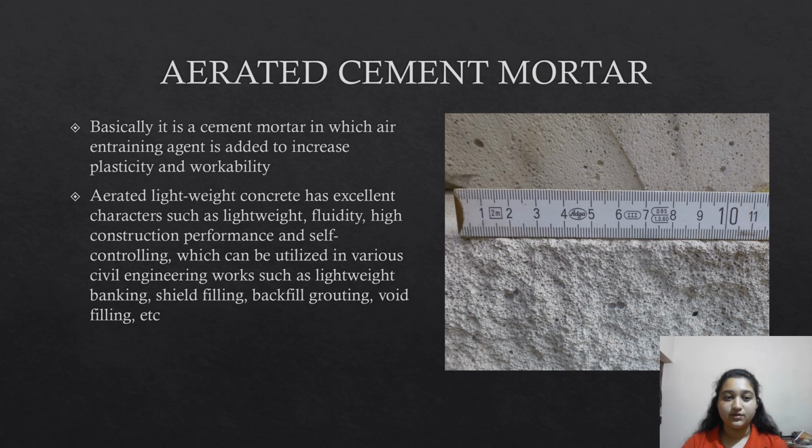Aerated cement mortar. Basically, it is a cement mortar in which an entraining agent is added to increase plasticity and workability. Aerated lightweight concrete has excellent characteristics such as lightweight, fluidity, high construction performance, and self-leveling, which can be utilized in various civil engineering works such as lightweight banking, shield filling, backfill grouting, void filling.